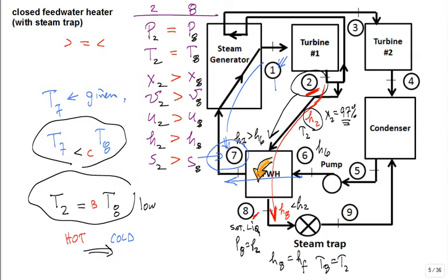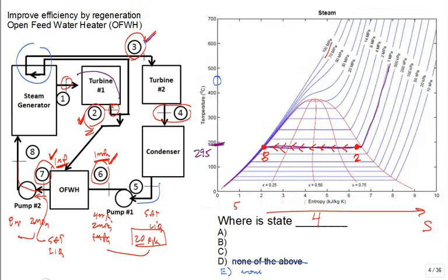Okay, let's go to this. I have to go back and reuse this diagram. Let's say we bring it out of the boiler at around 450 at 8 megapascal. So we're right about there. We talked about if you bring it down to just maybe 4 megapascal or 2 megapascal, you're in the superheated region.